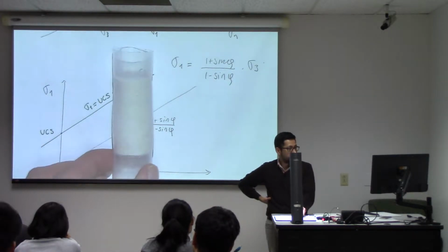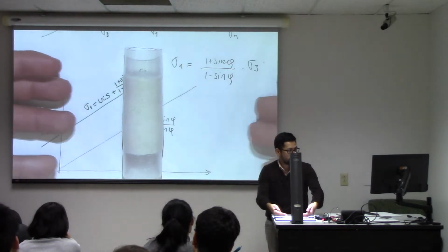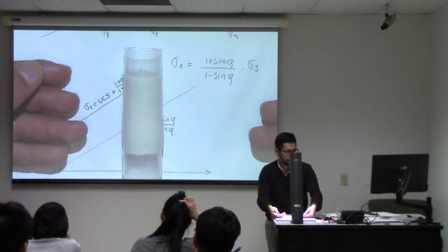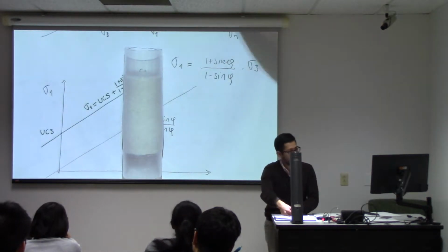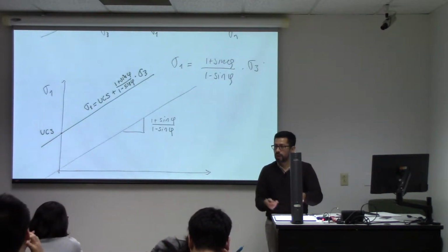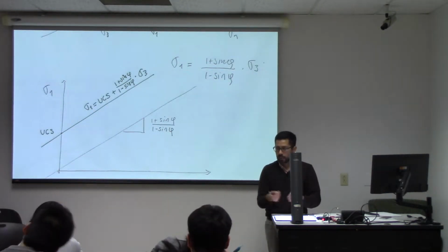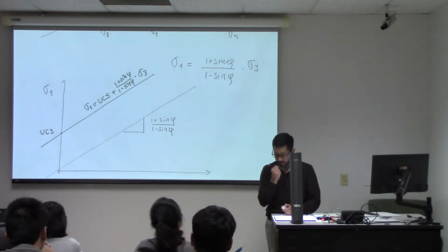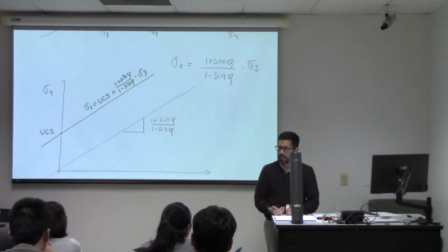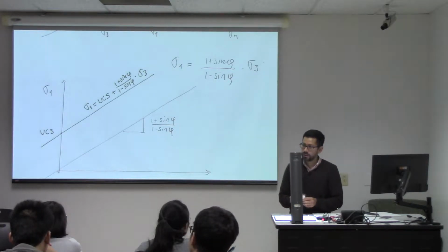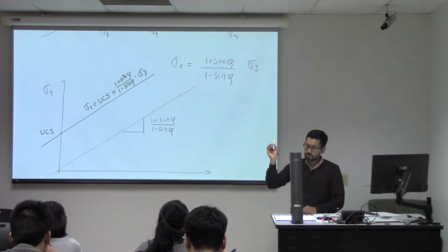So we would apply pressure on the sides that is going to be higher than 1 atmosphere, and you load it in this direction. The jacket allows a difference between the outside confining pressure and the pore pressure, so the difference of that is going to be the effective confining stress, or the minimum effective stress. So this is what you use for running this test.